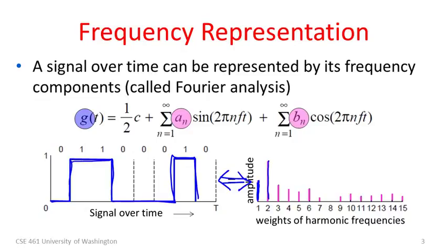This first frequency component is a fundamental wave that oscillates maybe over the time period of the whole signal here. This second one, labeled 2, the second harmonic, means to add a component which oscillates twice as fast and with a higher amplitude. Then we're going to add another component which oscillates 3 times as fast with a smaller amplitude, and so forth. If we sum up all of these different oscillating frequencies, then, believe it or not, we'll get this equivalent signal on the left.